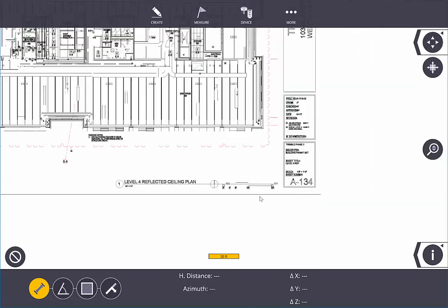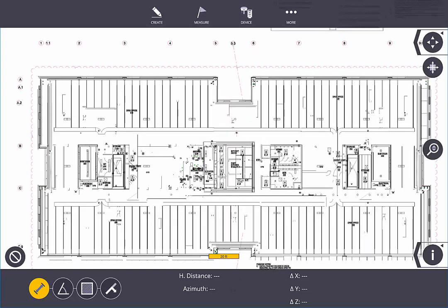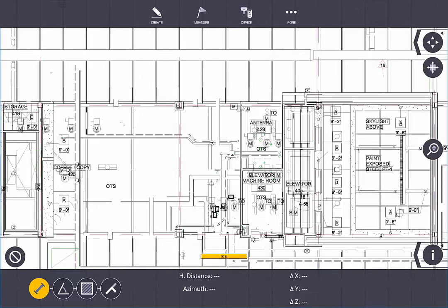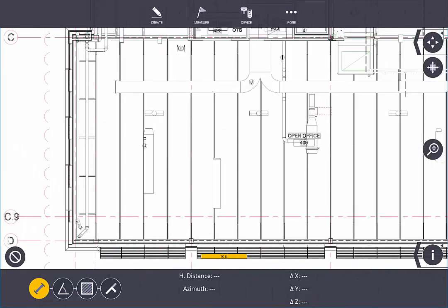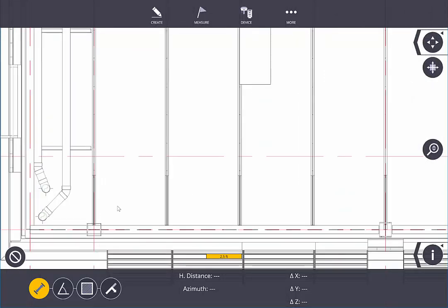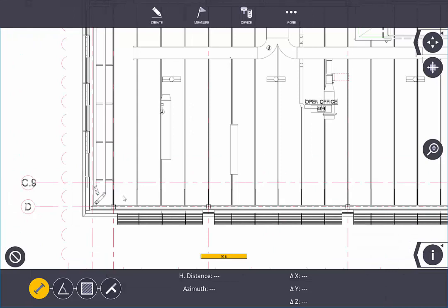Okay, so I'll clear this out. The next thing I need to do is start creating some points that I can lay out on the job site. However, before I create those points, a very important step is to give myself some control points. Now, control points are basically a point that I can select from the map or the drawing file that I can physically get to on the job site. That's very important because our instruments require control points to get set up.